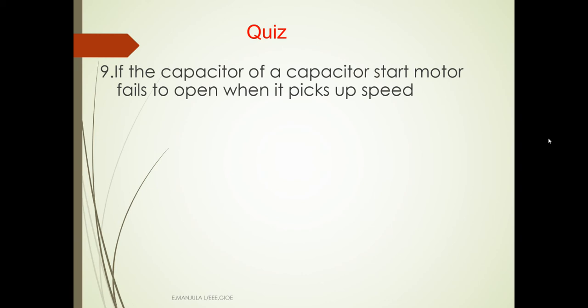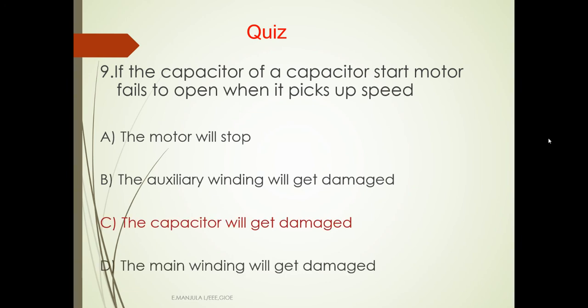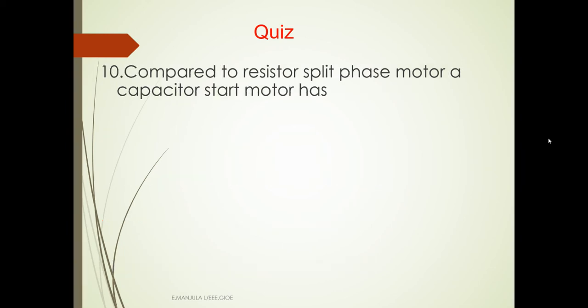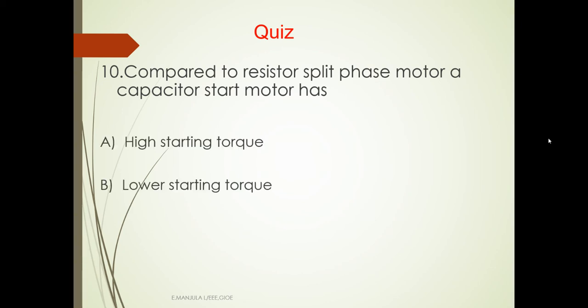If the capacitor of a capacitor start motor fails to open when it picks up speed, the capacitor will get damaged. Compared to a resistor split phase motor, a capacitor start motor has high starting torque, obviously.